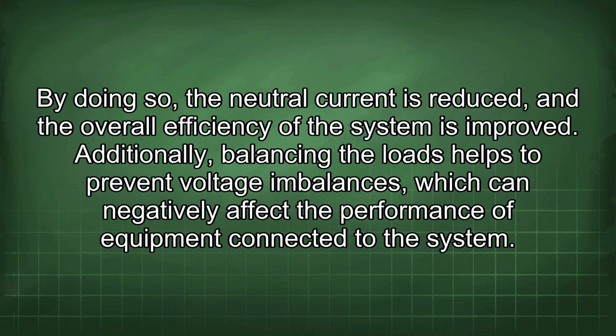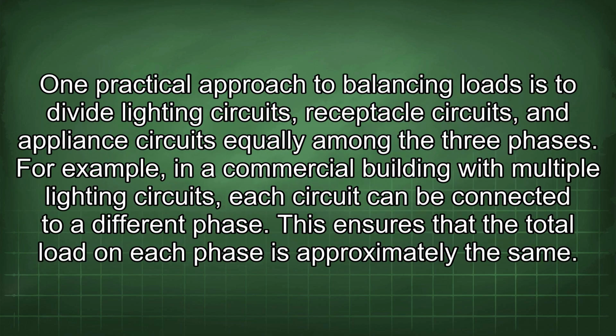Additionally, balancing the loads helps to prevent voltage imbalances, which can negatively affect the performance of equipment connected to the system. One practical approach to balancing loads is to divide lighting circuits, receptacle circuits, and appliance circuits equally among the three phases.